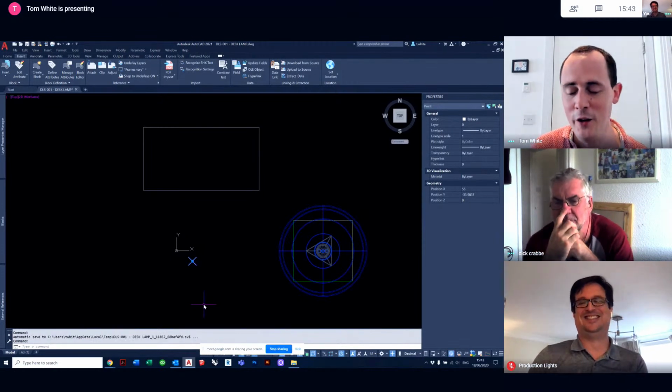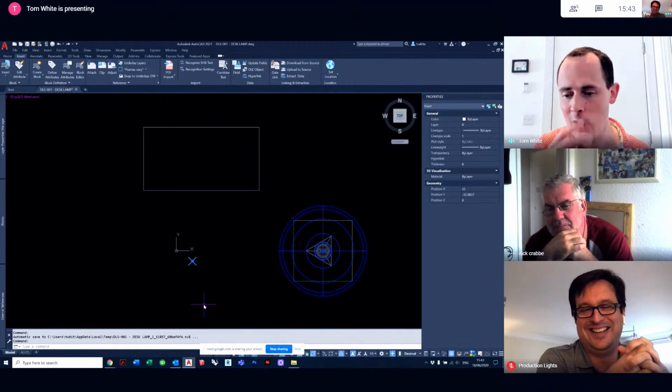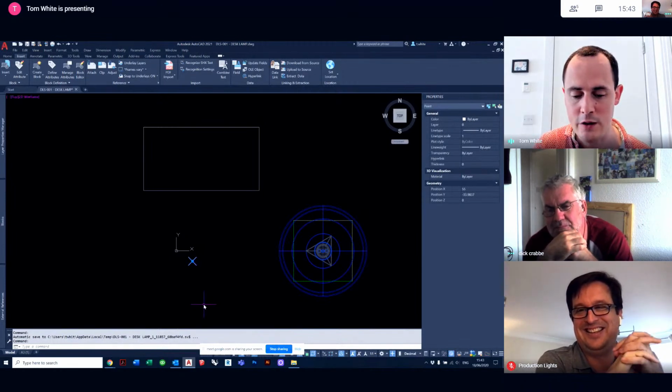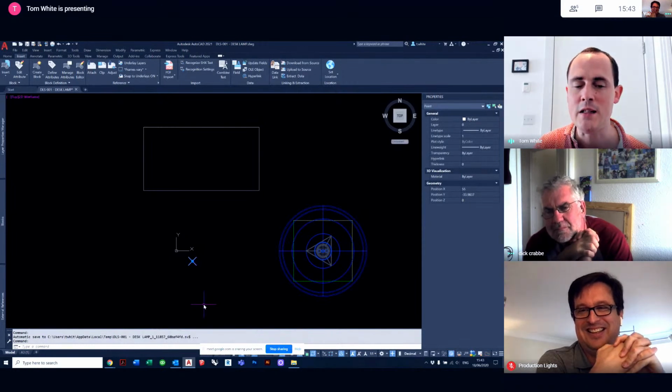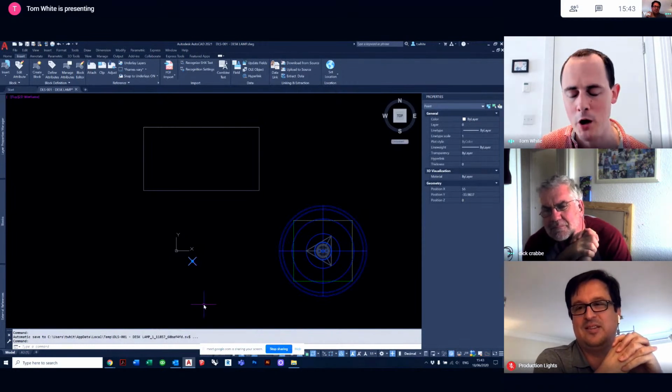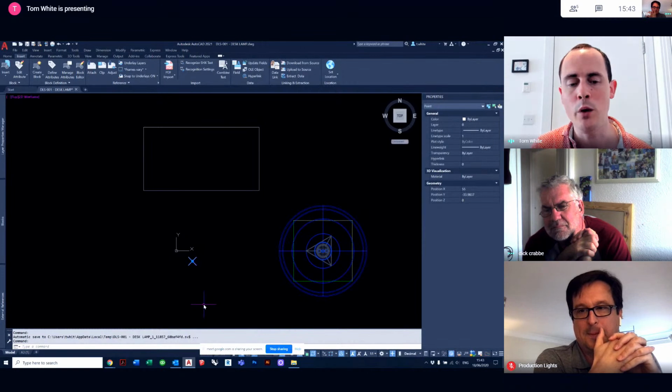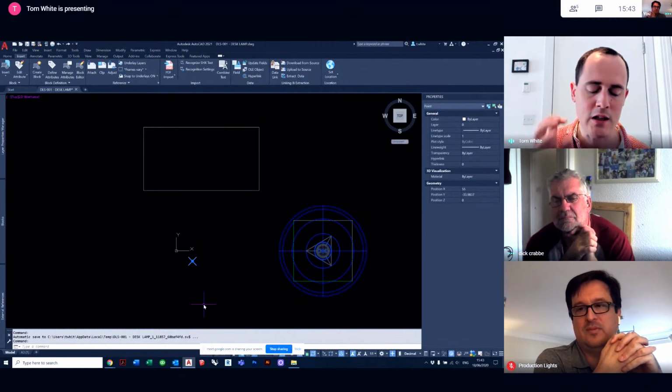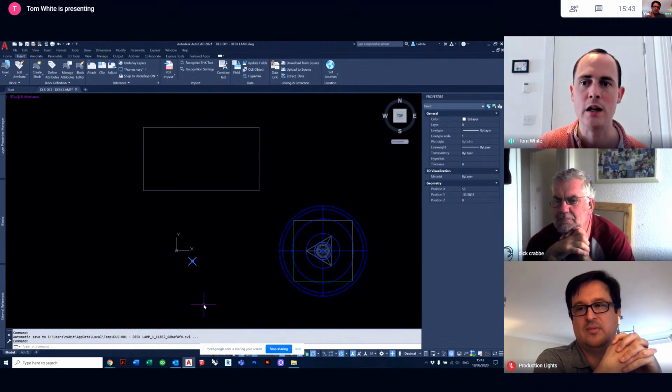It's fascinating you mentioned that, because, again, please interrupt if you have a different opinion, Dom, but I believe that's a similar circumstance where, when you purchase the DXF file of an ordnance survey map and use the XREF or external reference command to put it in AutoCAD, at a glance its location looks like a random distance from the 0,0 of a drawing.